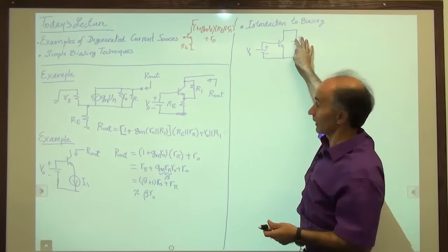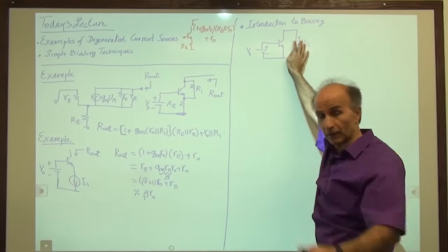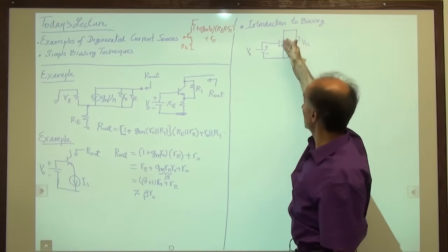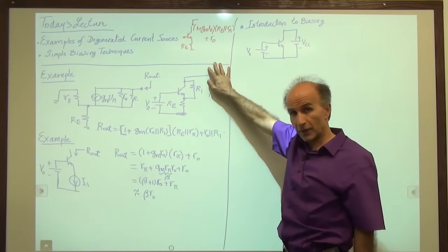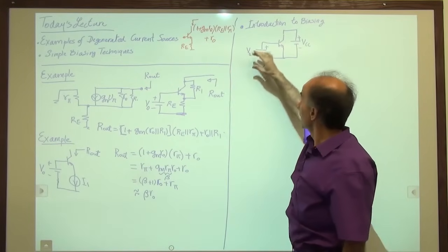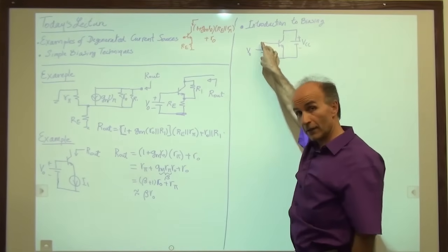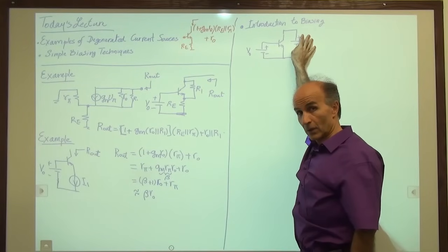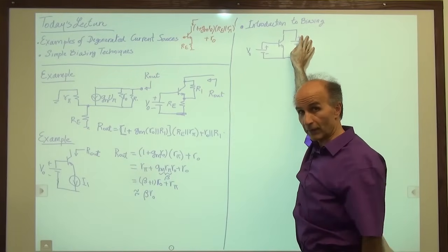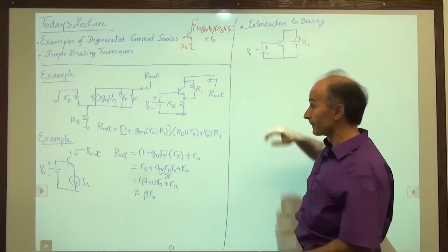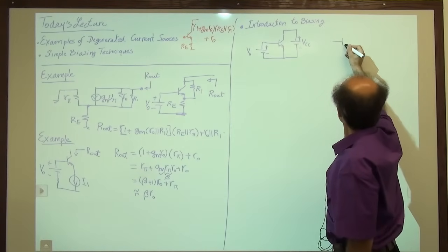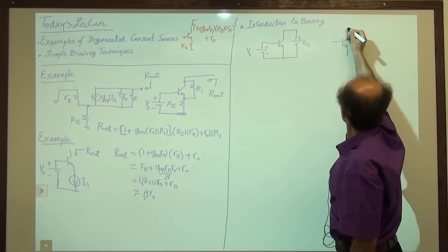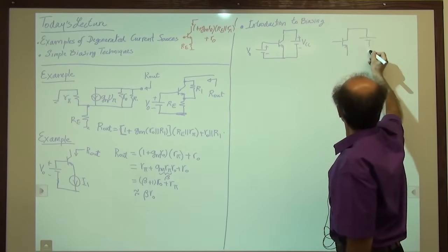Let's say this is the battery. This battery feeds everything. It feeds the collector current, it feeds the other parts of the system. So the question is, can I generate the voltage that I need here from this battery? And if you remember that we have resistive dividers, yes, why not? So let's do it this way. We draw the transistor again. Here's our battery.